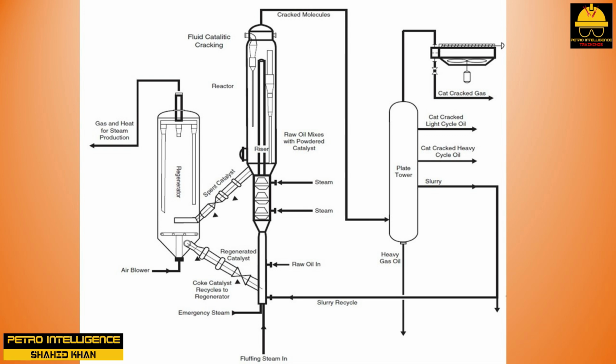4. Line up the reactor overhead vapor line to the main column. 5. Start the main column bottoms pump. 6. Start the overhead gasoline pump.